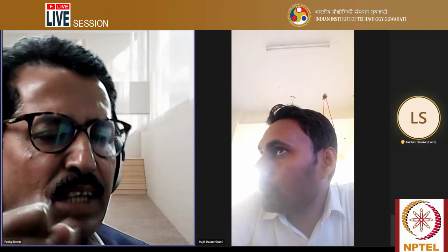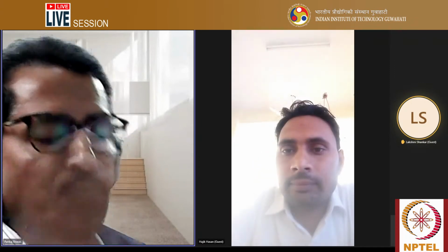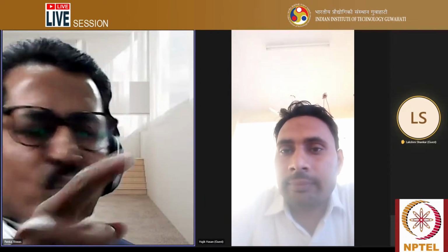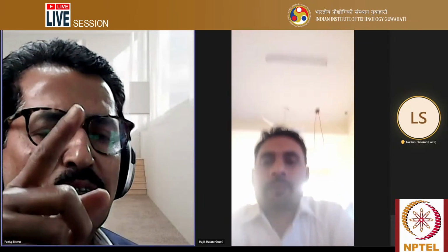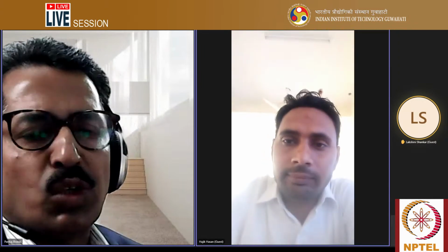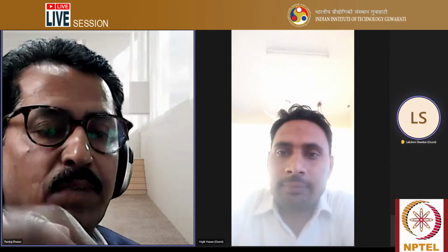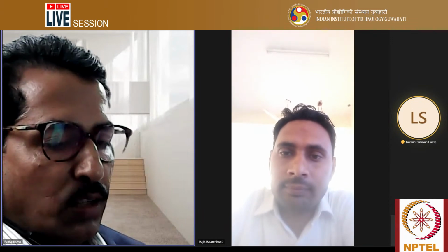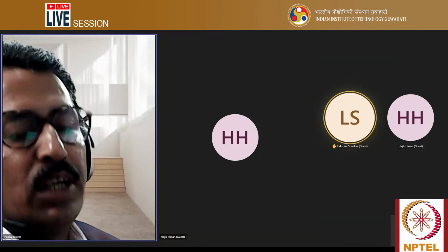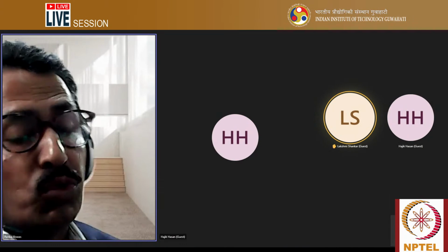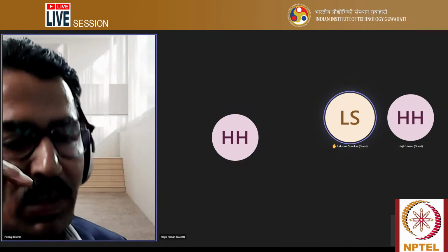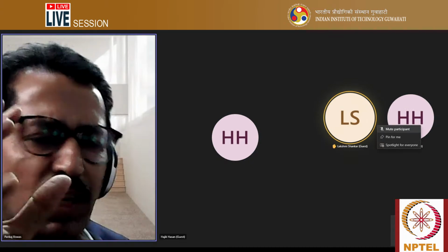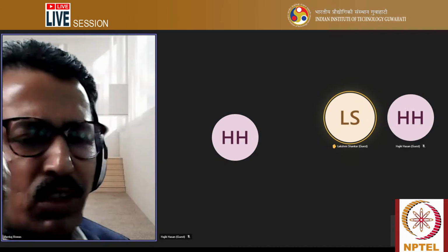That means each and every flux has some important features. I explained those things very clearly, as you can see. If you want, I can show you that also. I have told you that for very sophisticated types of welding operation, you should use basic electrodes. Understand? For low cost applications, you can use cellulosic types of electrode.